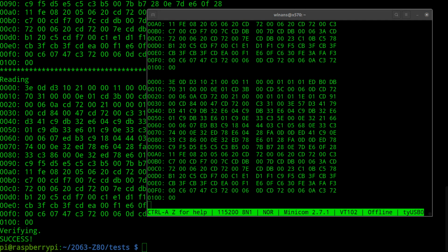And with that, I think we pretty much can wrap this. I'm going to leave the timer mode variant of this as a test for the viewer. Feel free to play around. You can even just take X2 out and stick it in X1, run your whole Z80 at 1.8432 megahertz. It'll go slower, but you will then have a phi clock that's running at 1.8432, and you can run that through the CTC in timer mode if you want.